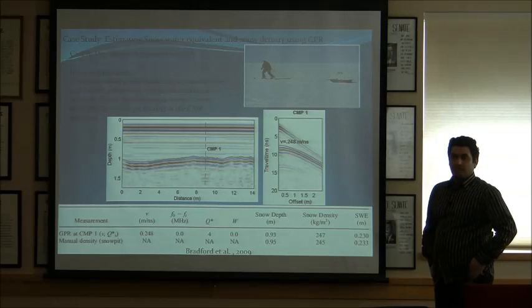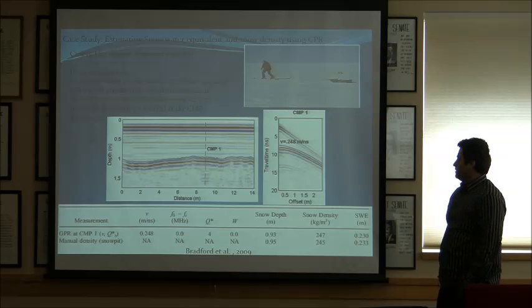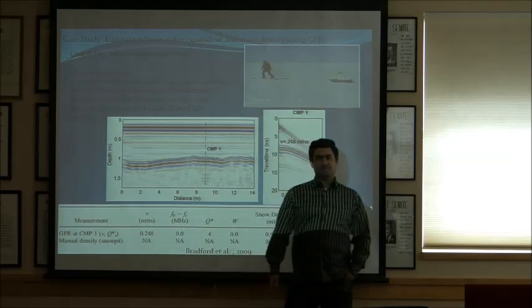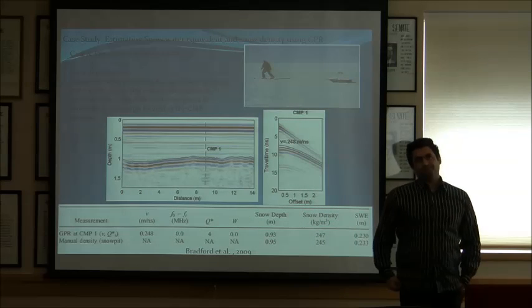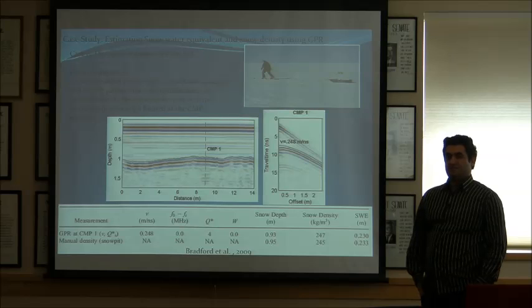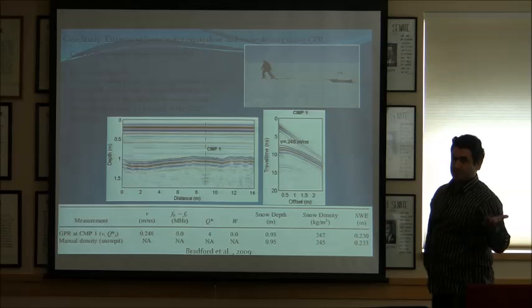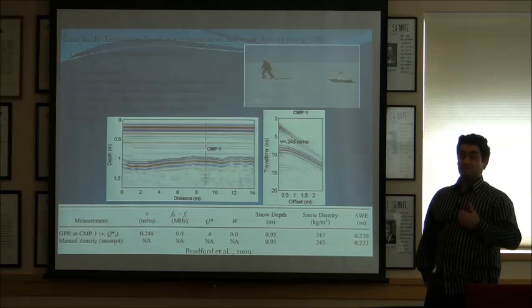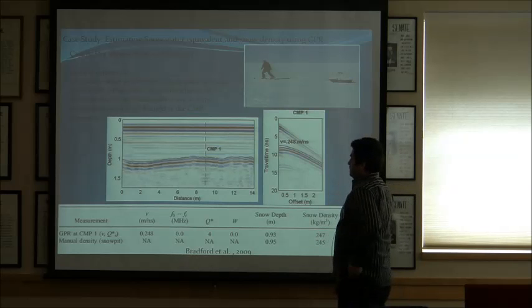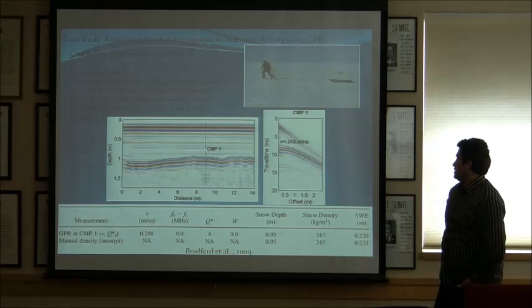Can I ask a practical question? How fast can you drag a GPR sled? Okay, for this study, they make measurements every 5 centimeters. But you can attach it to an ATV. Some people attach it to an ATV and they run slowly. But in case you are too fast, the system is smart enough to make a beep to warn you that this is too fast. But most people drag it like that, since they need high resolution measurements.